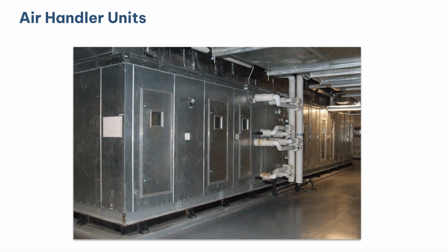An air handler unit is an excellent place for a wireless system. They're in a confined space usually that is not able to be opened during operation due to lack of guards or process conditions. Typically run at a constant speed, sometimes on a VFD, but typically a constant speed. And the wireless can usually get to the outside of the case without drilling any holes or running any conduit. So wireless would be an excellent option for these.